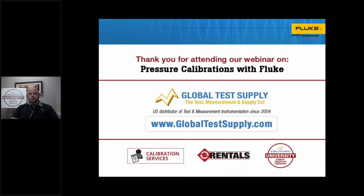of calibration. If it winds up being out of calibration and you're on a quality program, it can be pretty expensive from a time perspective to work back through your workload in reverse order to make corrective actions on calibrations that may have been done out of calibration by that bad standard. Again, a 1-year calibration cycle is typical, and some of our pressure modules have a 2-year specification. If you choose to go to a longer interval, you should make adjustments for your overall accuracy. Extending your calibrations will lower the accuracy of your standard.